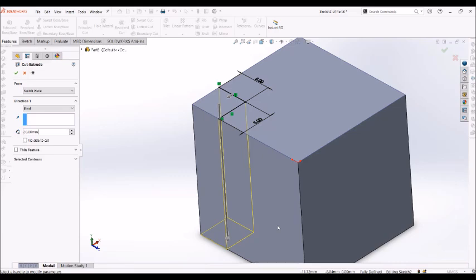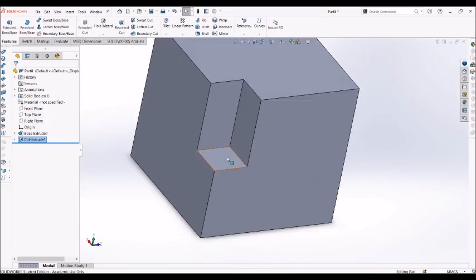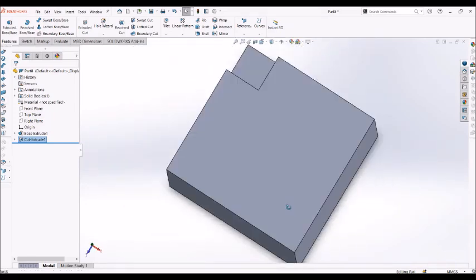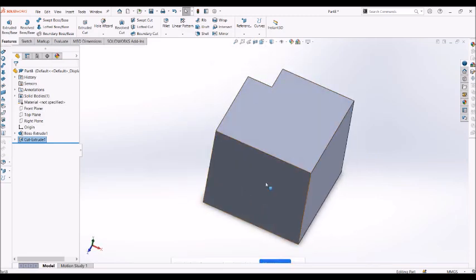So what you can do in SolidWorks is use a formula to calculate depth. We know it has a total depth of 20 millimeters. So we type in 20, and then we use the slash sign to divide, 20 divided by 2, and if we click the tick, see, it works it out as 10. And if we click the tick again, it'll cut that little cube 10 millimeters down our big cube. So there you go, you've got our first part.